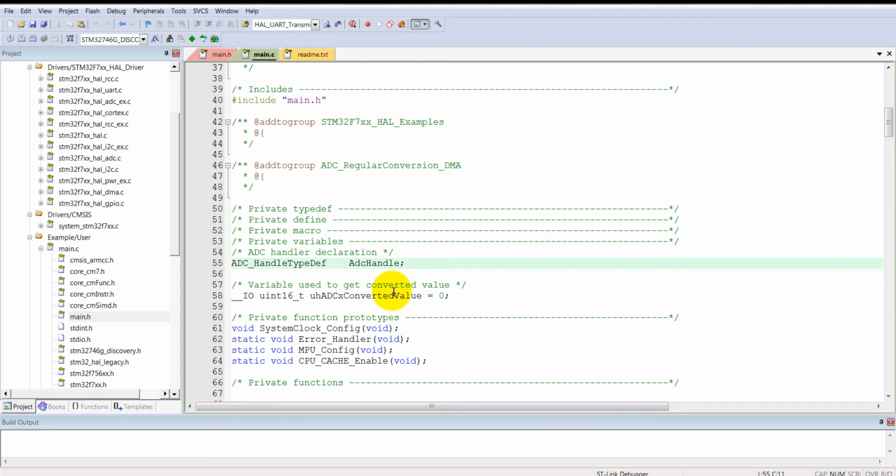And also it supports the continuous mode and the discrete mode, DMA support, and also 8-bit resolution, 10-bit resolution. And also it has a successive approximation type of ADC. So as you know, the successive approximation type of ADC takes 1 clock cycle per bit.